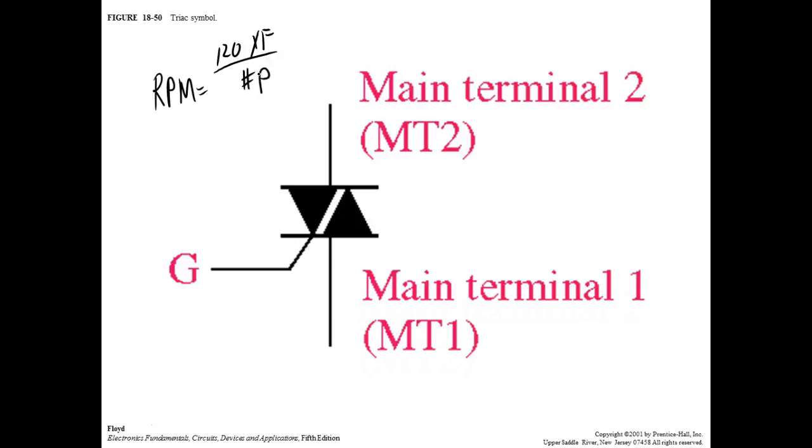So you see there's no voltage in there. The problem with an AC motor is that if you put more voltage on it, it's not going to run any faster. And if you drop the voltage down, remember torque varies with the square of the voltage. You can stall your motors just like that.